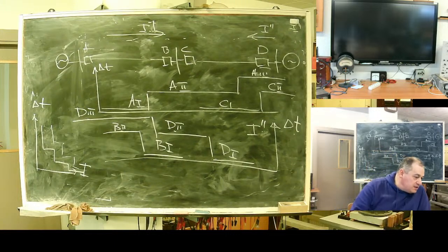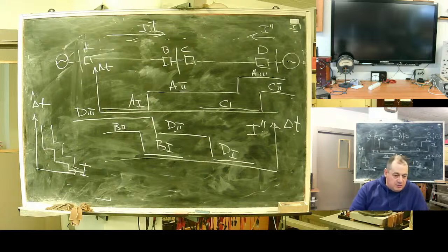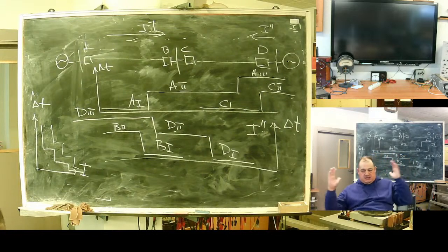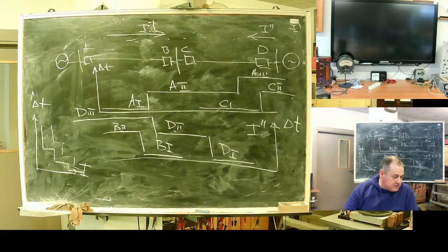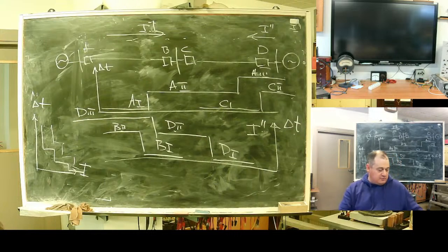Can a time dependent zone be directed? Yes, it can be directed or polarized. Some scholars use not the term directed but polarized. Polarizing signal for the relay is our voltage. And please, don't make me go to jail. Do not use current difference scheme on a distribution network where delta star transformers are used. If you do so, I will kill you and will need to go to jail.